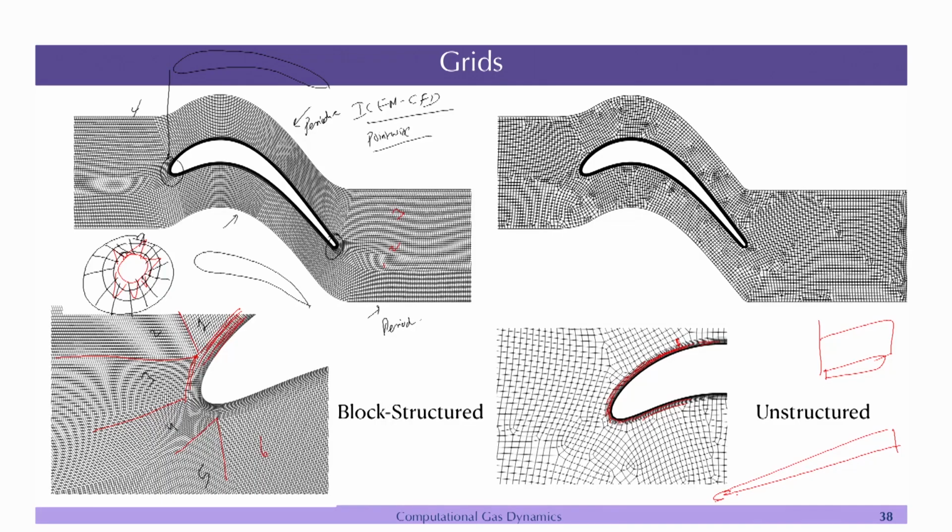So, you need to put in effort for making the grid, and if you look at this particular grid, you basically have elements. These are the quad elements. Sometimes you will have tri elements, which have only 3 sides. Here there are 4 sides. And then you have different orientations at different places. Actually, a mesh can become much more complicated than this. Let us say the example that I talked about in the beginning, you have a slat and a flap and a wing, there are several gaps, or multi element aerofoil and all those things.